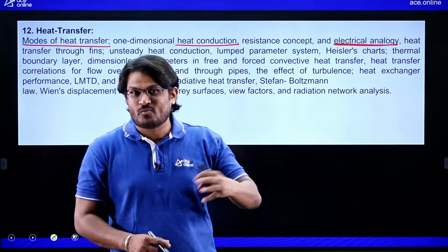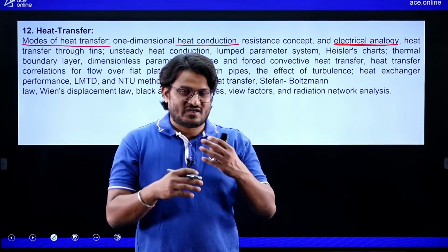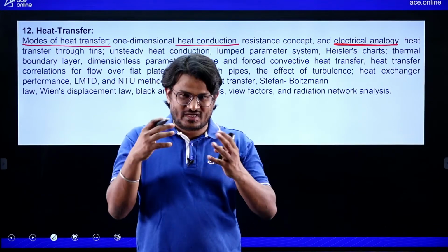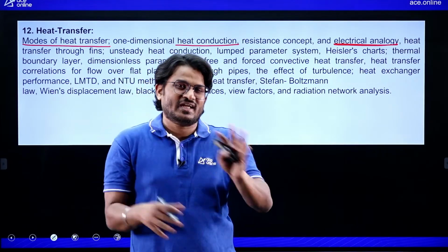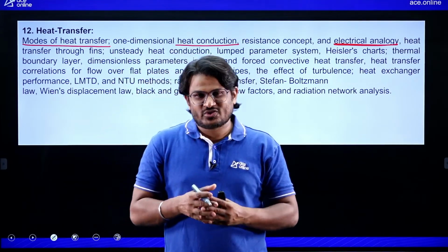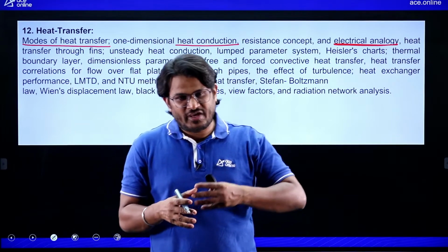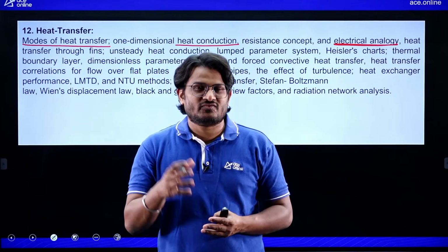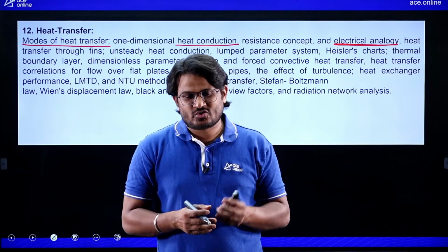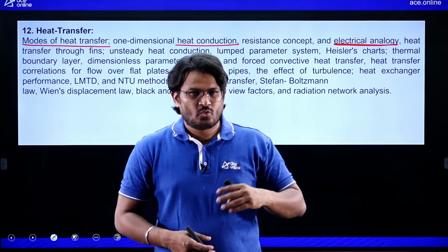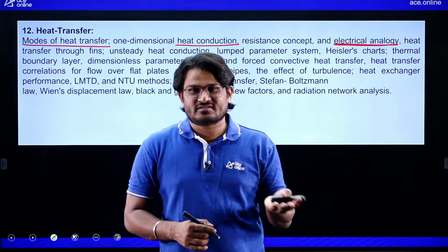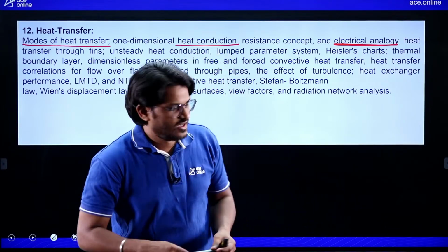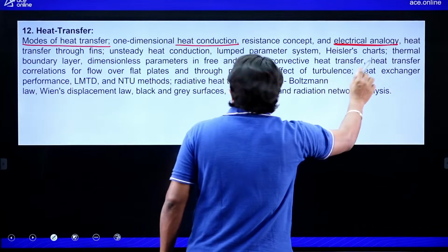Actually, whatever Ohm's law is there, that delta V is equal to I R, so I is equal to delta V by R, that we will paste in a heat transfer point of view. The way current is flowing, similarly we are taking it as heat. So current is replaced by heat, voltage difference is replaced by temperature difference, and resistance is replaced by thermal resistance. So this electrical analogy is given.